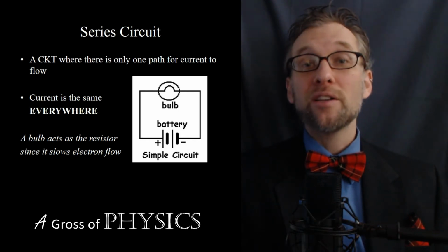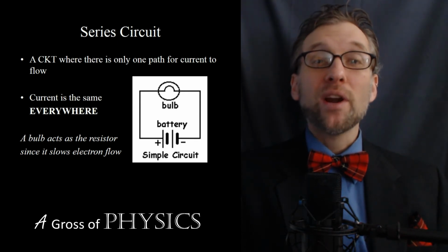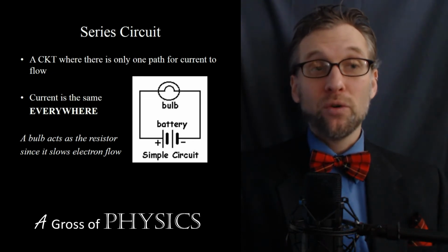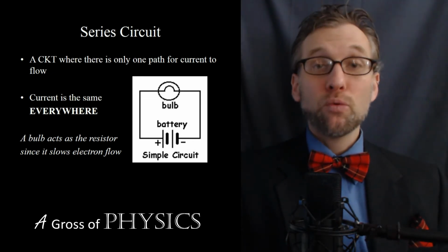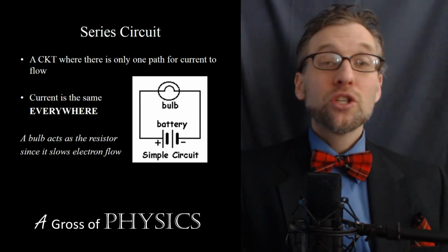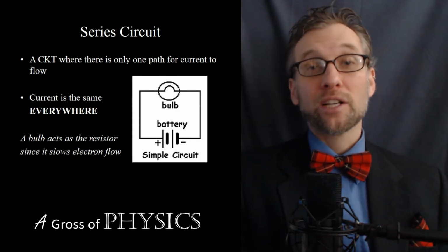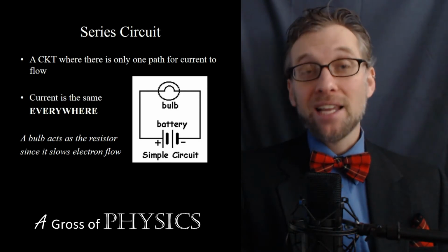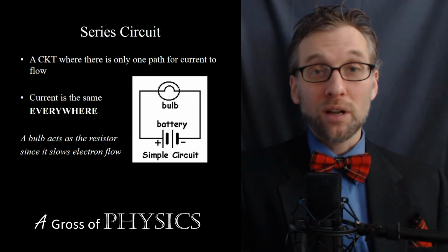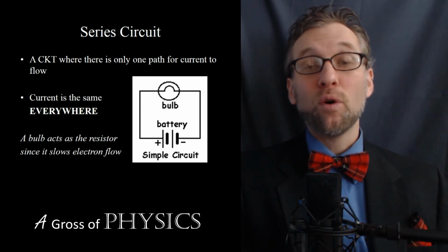That's because what you've done is effectively turn the switch off for that section. When you have a break in the circuit, the electrons don't have a way to flow past that. The push won't provide any push anymore, and the electrons will just stop. So a series circuit is one single path for the electrons to travel. If any of the light bulbs turn off, for example, if you have incandescent bulbs and you unscrew one, the rest will stop working. So you can tell if you have a series circuit if you remove one component and the rest stop functioning.